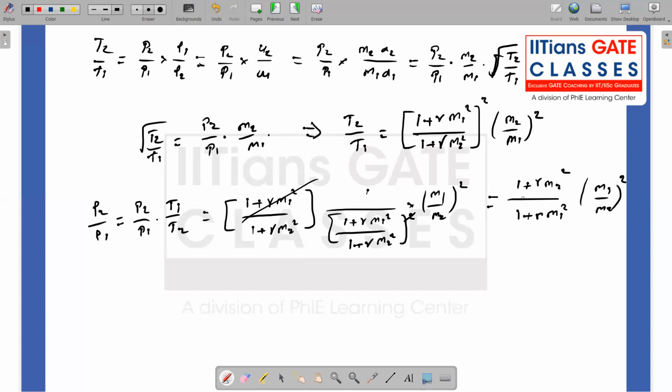Straightforward. So we got P2 by P1, T2 by T1, rho 2 by rho 1. How can we calculate P0 2 by P0 1? That is again straightforward. I am not going to show you the derivation part and all. I am just going to show you how you can do it. For P0 2 by P0 1, you can divide and multiply by P2 and P1. So P0 2 by P2 into P2 by P1 into P1 divided by P0 1. So P0 2 by P2 is nothing but a point definition, right? At the point you are applying.